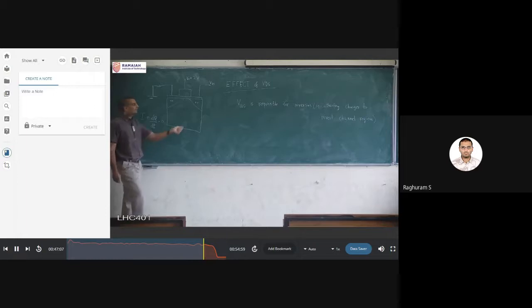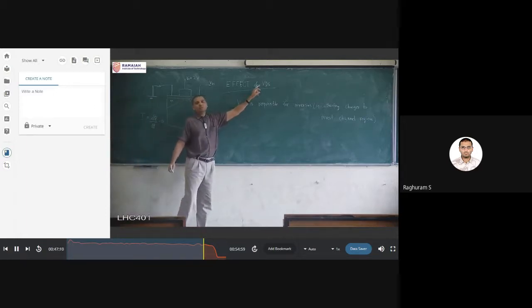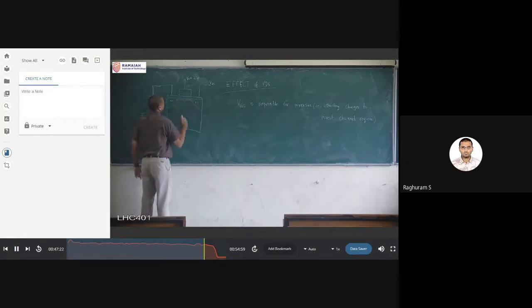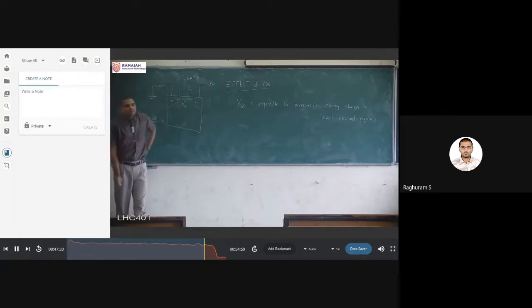How do we get the current? That is why we have the drain source voltage. Now this drain source voltage is in the horizontal direction. This electric field, because it is between these 2 terminals, this electric field, okay, this is the E, the electric field between the drain and the source. Now that electric field is there, it will move the electrons in the horizontal direction, and we will have some non-zero value. Now is when the current is flowing.